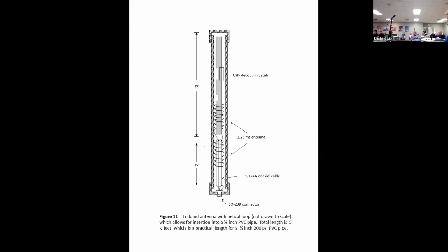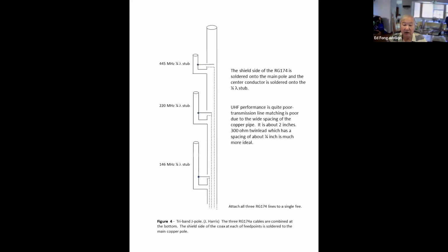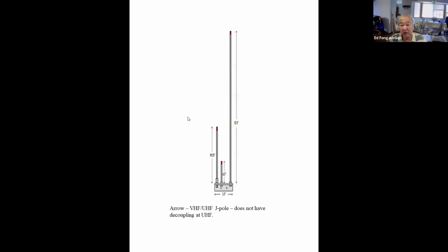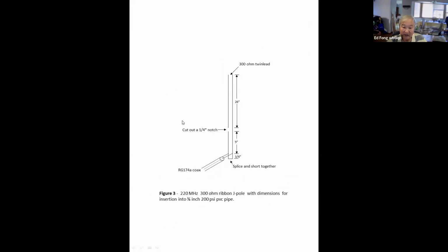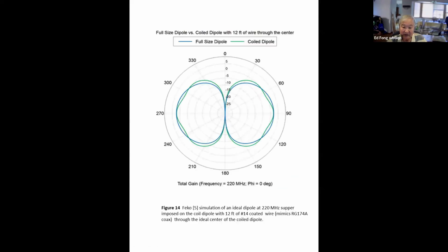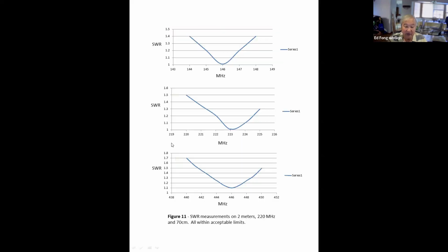Yeah, but normally you make a J pole out of 1/2 inch copper. What would happen if you made it out of 1 inch copper? I see. You're saying in the copper J pole like this. This actually has pretty wide bandwidth because it has a low Q. Again, if you use twin lead, I think a lot of people do, here it is on 2 meters.